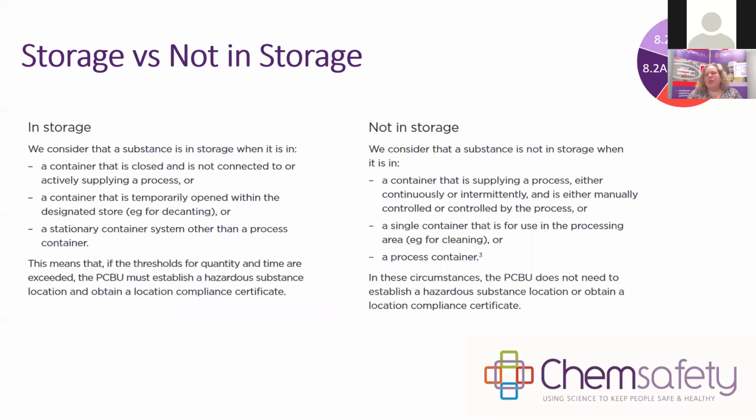So this is WorkSafe's current position. They consider a substance to be in storage if it's in a container that's closed and is not connected to or supplying a process, if it's temporarily opened for decanting within the store, or if it's a stationary container that's not a process container. So if it's a tank, then it would be considered in storage. So if you're in storage, then you need to establish your hazardous substance location and get a location compliance certificate.